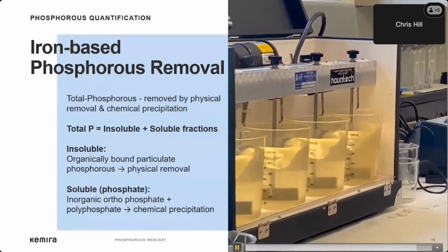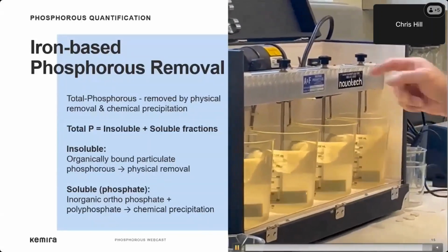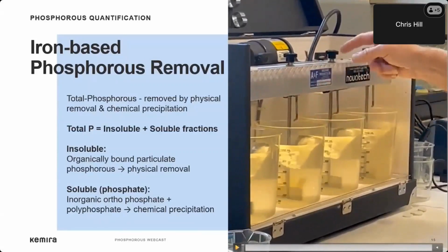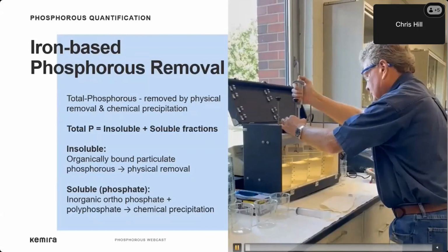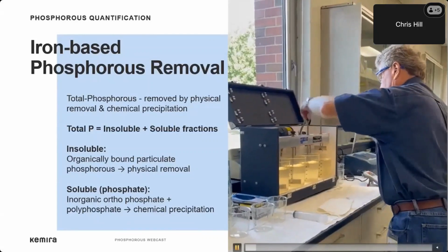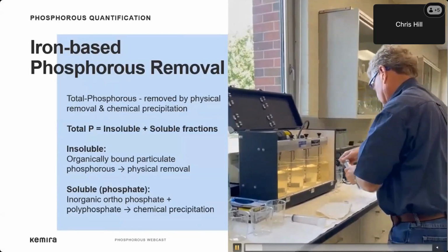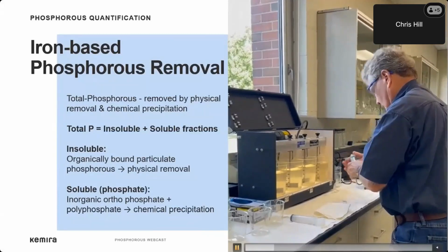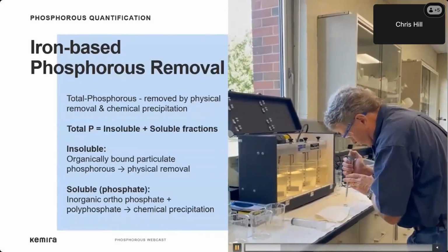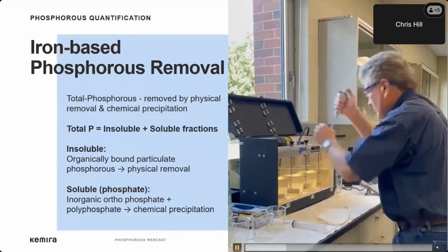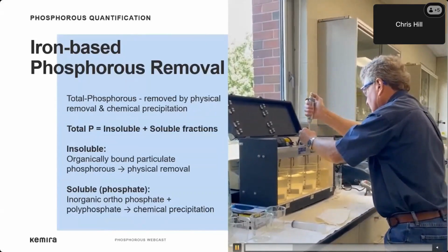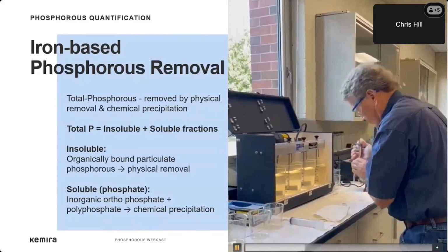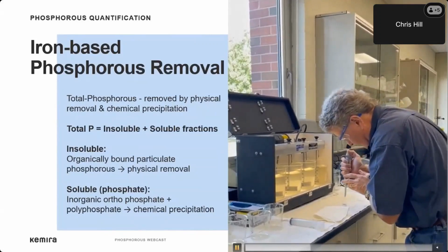The ratios of coagulant to soluble phosphorus and phosphate for Fe+3 iron are 1.80 for phosphorus and 0.59 for phosphate. When dosing iron, the presence of soluble phosphate indicates an insufficient coagulant dosage. The presence of insoluble phosphorus, also known as organically bound particulate phosphorus, in the wastewater can be caused by poor settling conditions. This issue can be addressed through adjusting hydraulic loading rates, mixing adjustments, introduction of polymer dosing, or providing additional flow capacity.